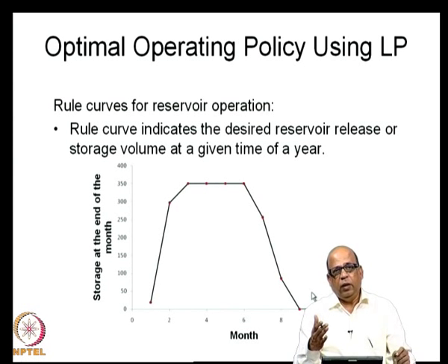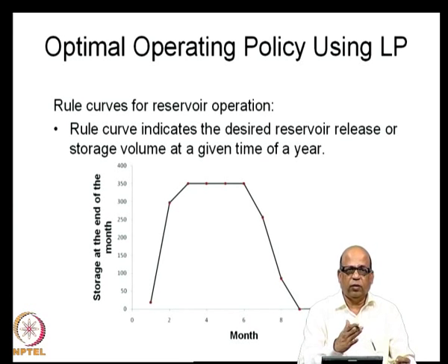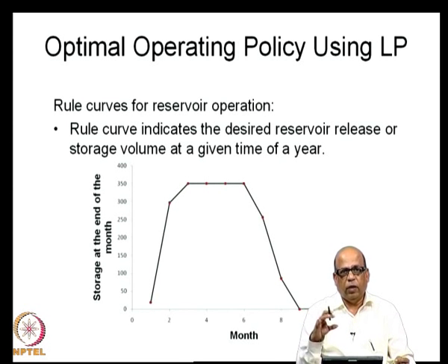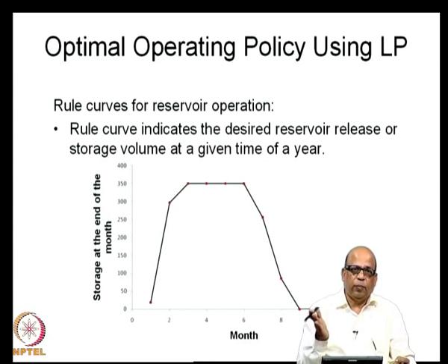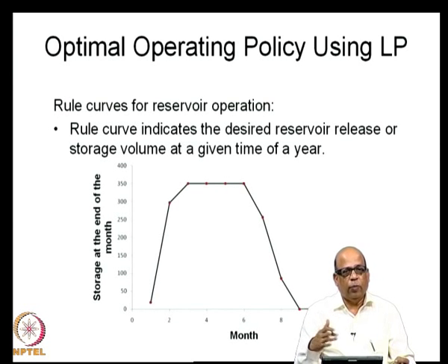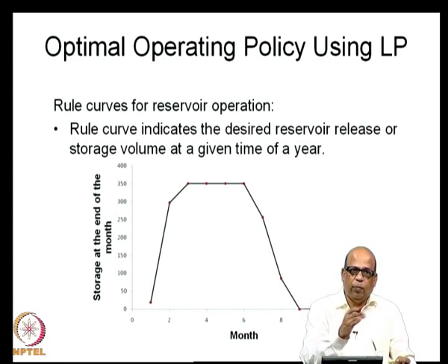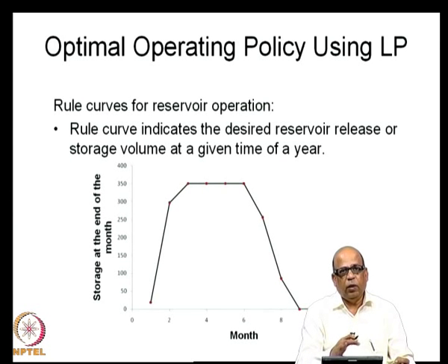Now, in realistic situations, you will not have such simple demand patterns. You may also have a flood season, you may also want to meet industrial demands during certain time periods, which may have higher weightages. You may want to meet municipal demands for drinking water purposes during certain periods, which may have much higher weightages and so on. So, you may have multiple objectives. Keeping all those things in mind, you can formulate the optimization problem and then arrive at the reservoir operating policy, but the general principle remains the same, that you formulate the